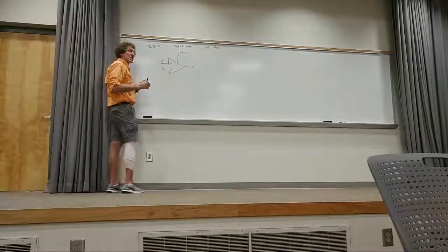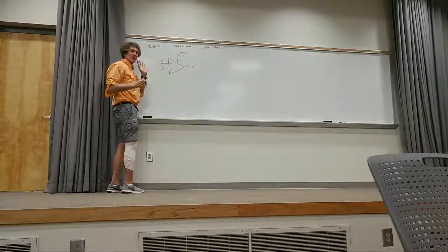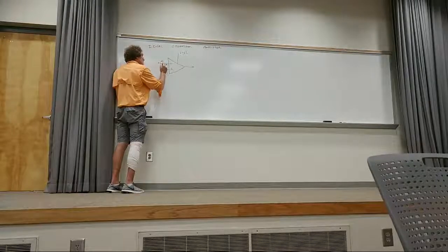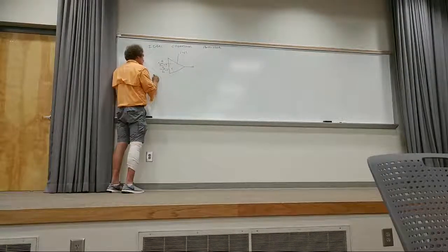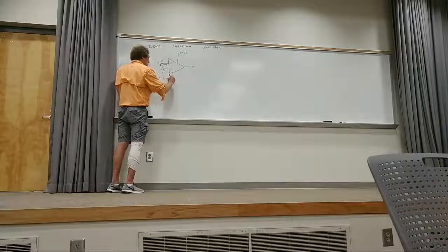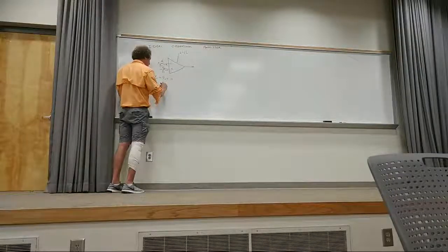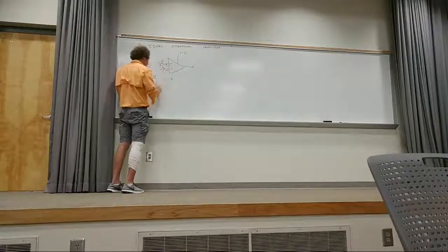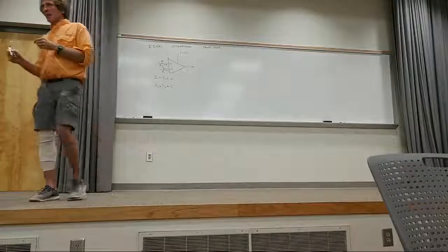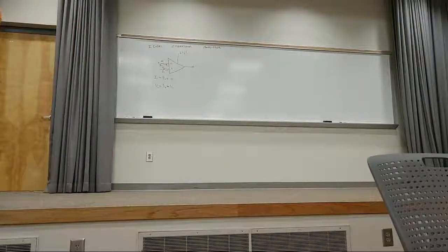And if there is, the op-amp will go into saturation and the whole circuit behavior falls apart. The second thing is there is no current. This would be I minus, and this would be I plus. There is no current. I minus equals I plus equals 0, and V minus equals V plus equals V1. There's no voltage difference. Now, no voltage difference, no current into it.